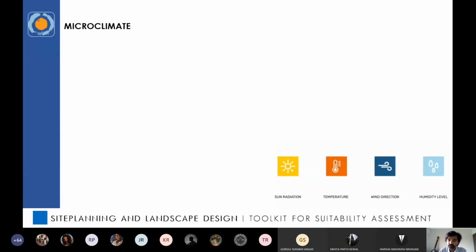Now, what is in our control? These finer aspects of microclimate are definitely in our control. Understand where the solar access areas are. Understand how much the temperature variation is within the landscape or within the built environment. It's always a great exercise, once you have done a project, that as time goes by you go back and keep analyzing it. You keep taking the readings and you keep understanding that in such a condition, when I did such a move, where I planted trees on this side, when I understood that this was a wind direction and I wanted to keep the winds there and not block the winds here, and so on.